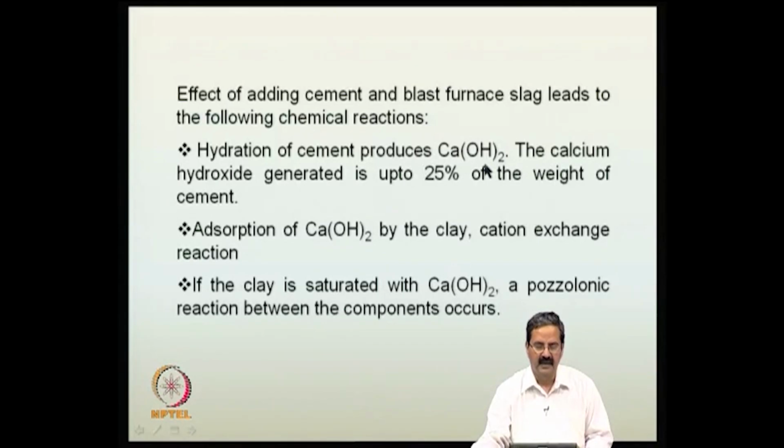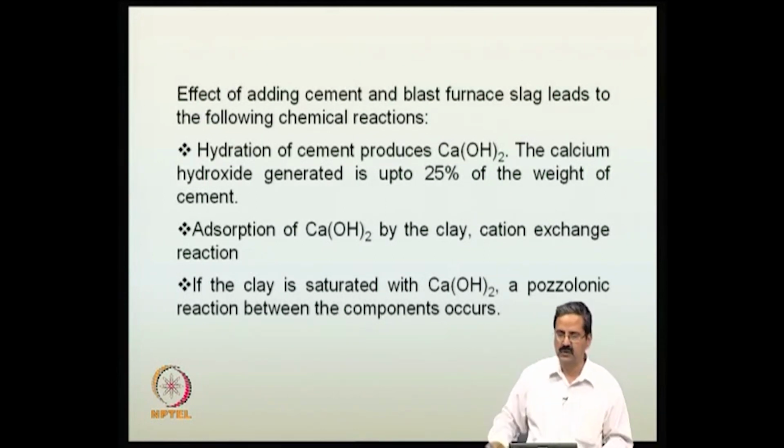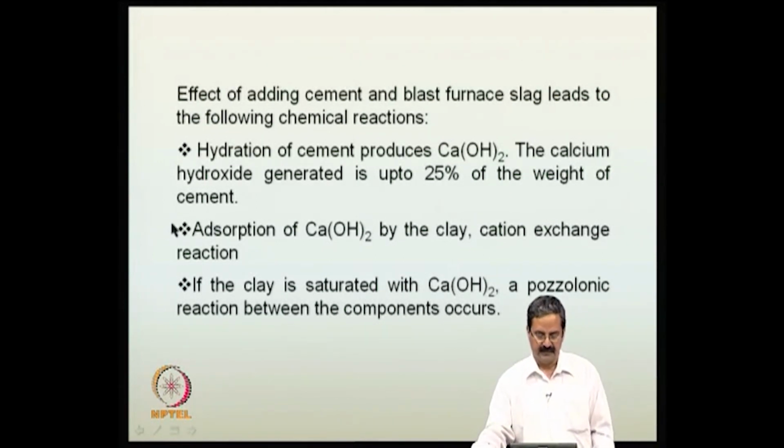It encourages flocculation, and some of the things we have seen, and absorption of calcium hydroxide by the clay and cation exchange also takes place. So, the addition of cement is similar to lime; the mechanisms are somewhat similar, but there is some more addition here. Sometimes even the pozzolanic activity is another important variable that comes in here. If the clay is saturated with calcium hydroxide, a pozzolanic reaction between the components occurs.